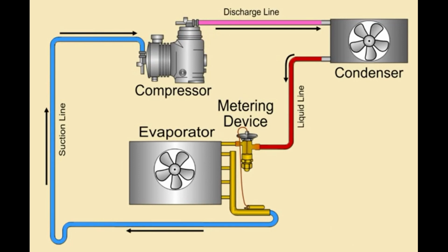As it leaves the compressor, it goes into the condenser, and it's basically a high pressure or a hot gas. Once it hits the condenser and you remove the heat, it goes from a gas back down to a liquid. That's called the liquid line. And that liquid line is the line that you'll see coming out that's going to go into your house. That's the one I told you has a filter system on it, your liquid line dryer. And it heads towards the metering device.